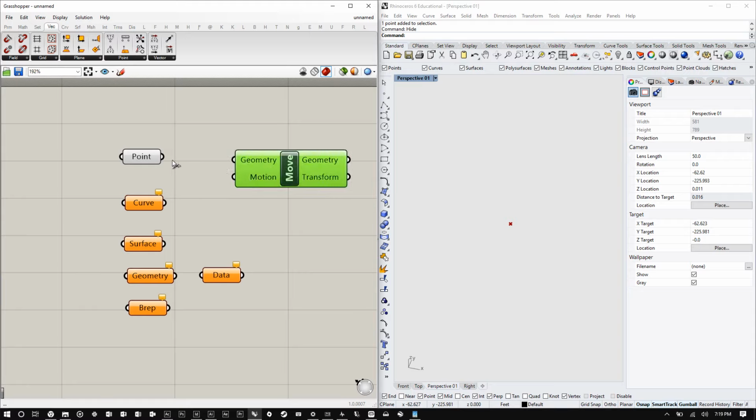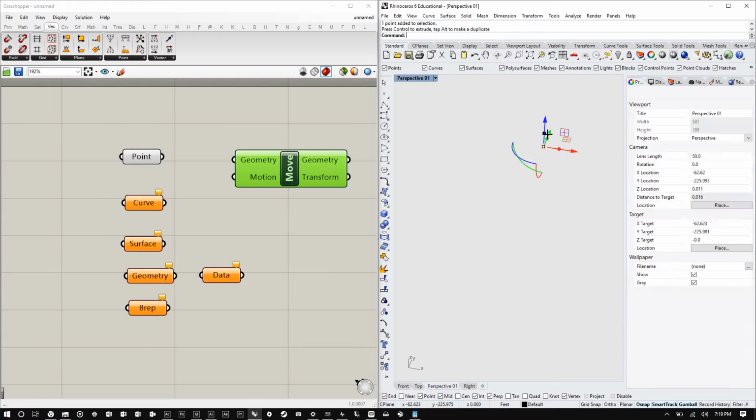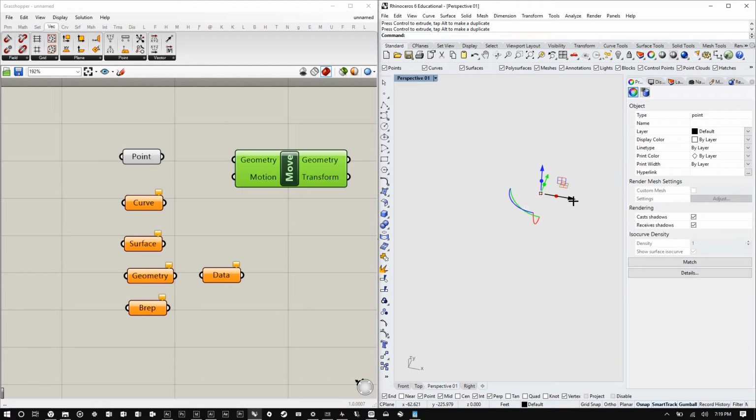Okay. So we've got our object reference, and real quick, I'm going to show the point I've hidden. When I select an object, I've got these move coordinate bars that allow me to move the object in one of the cardinal directions. That's the gumball in Rhino. If you select an object and go down to the very bottom right-hand side, you'll see a bunch of tabs at the bottom. You'll see grid snap, ortho, object snap, and then you'll see gumball. Select gumball and it'll turn that on.